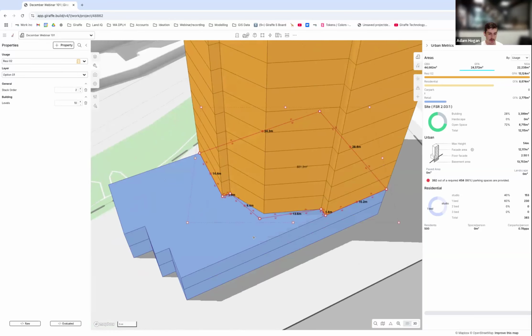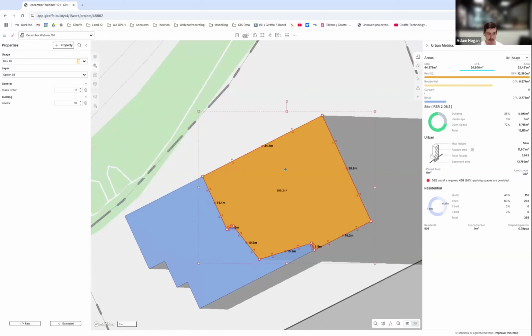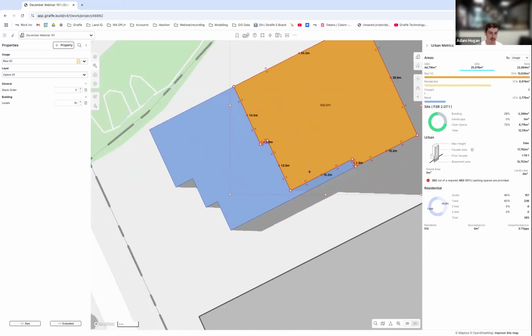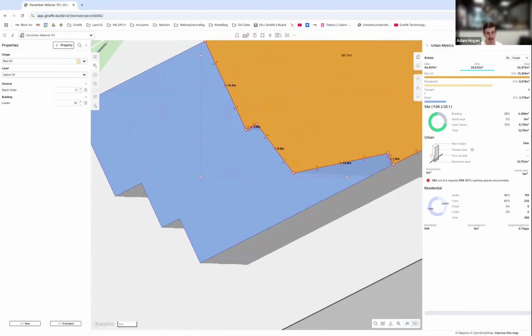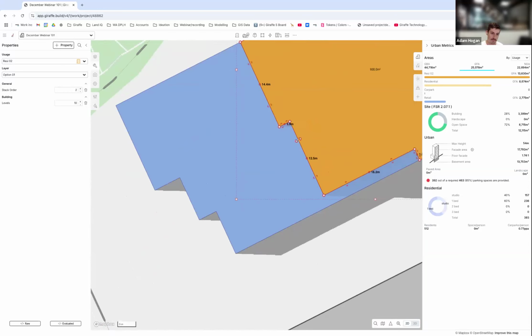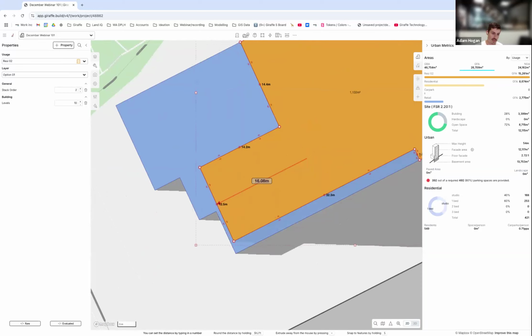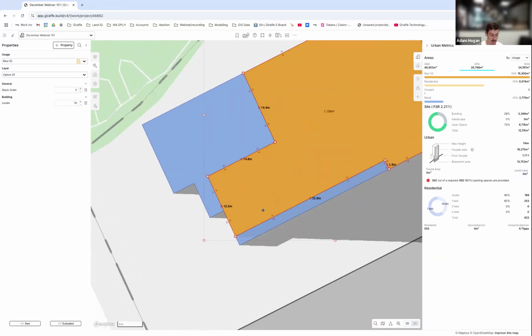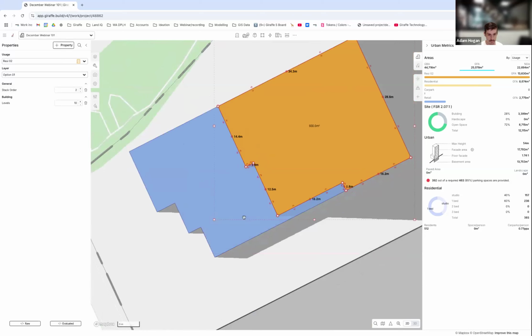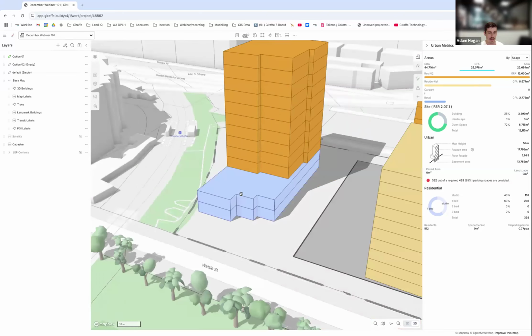When you are moving the nodes around, if I toggle into 2D mode, you can hold shift, which will snap you into your 90-degree plane, so you can bring it back to that rectilinear shape. If you drag it like this and then change your mind, you can hold shift to snap that back. If I wanted to drag this element out and make sure it aligned here, I can click and drag those arrows and then hold S on my keyboard to snap to that point, which gives me a level of accuracy when I'm playing with this design and changing things. I'm just going to undo that one there.